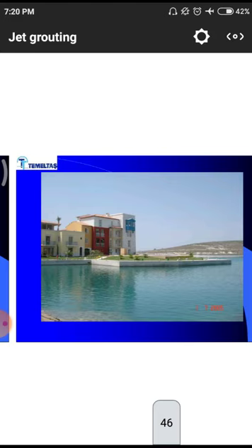Here also they have a small river or a small lake below the structure. Those conditions also we have to arrest by using different geopolymer sheets, piling techniques and grouting techniques.